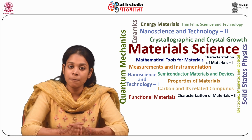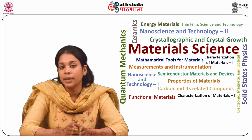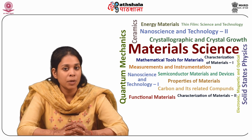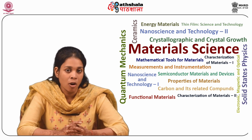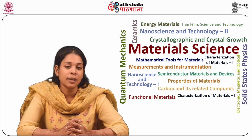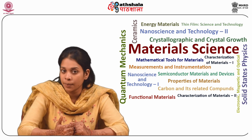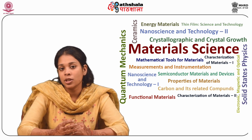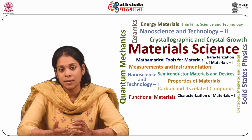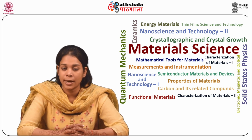In the capacitive pressure sensor, the way of fabrication is different from that of piezoelectric pressure sensors. In capacitive pressure sensors, a cavity is formed without any piezoelectric layer, and the cavity is surrounded by the top electrode and the bottom electrode. So the change in pressure will result in a change in capacitance, resulting in the generation of voltage.